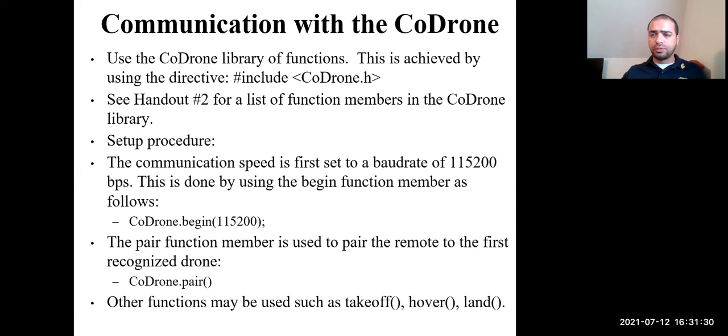So the first student pairs his or her remote controller with his or her drone. Then after that student finishes, the next student starts, and so on. You keep them far away from each other because it's going to search for the drones around, and the first one it detects is going to be the one that it communicates with. By the way, there is actually a parameter, nearest. If you put, for example, nearest, it's going to only pair with the one that has the strongest signal.